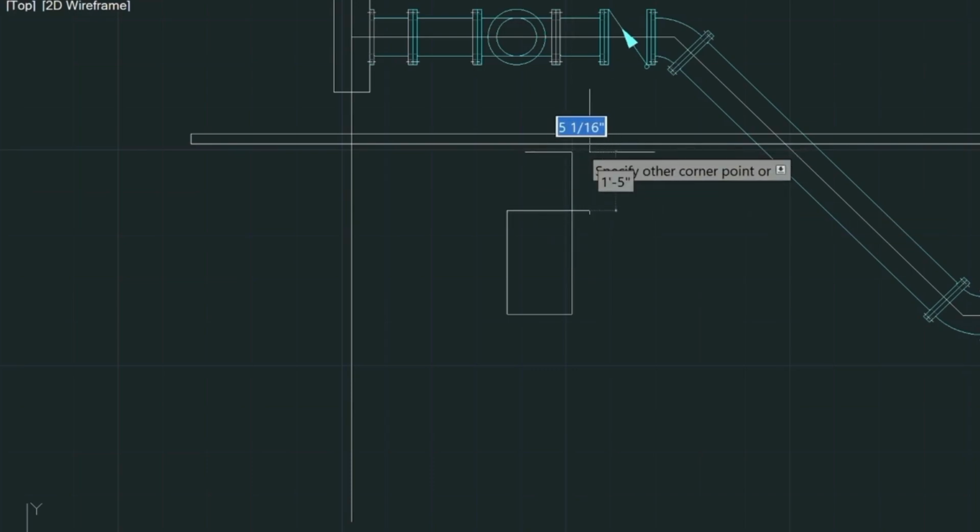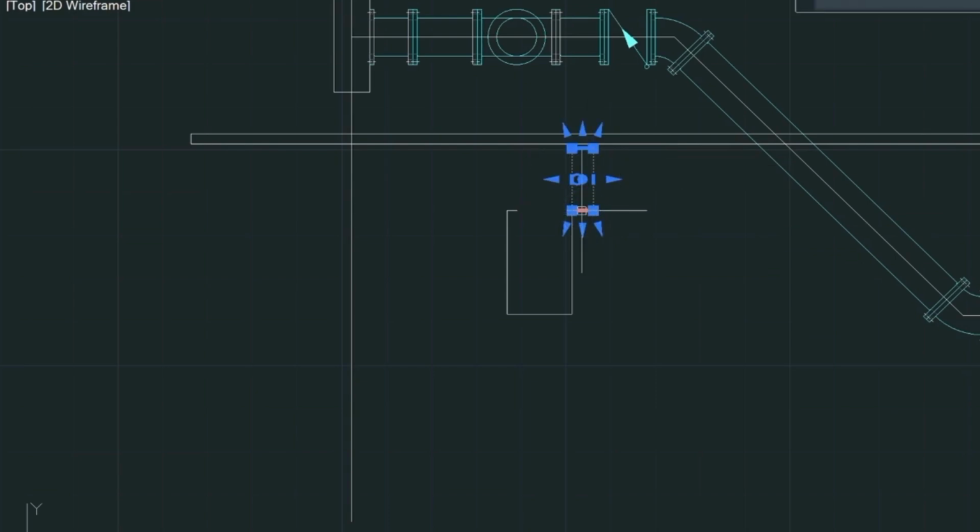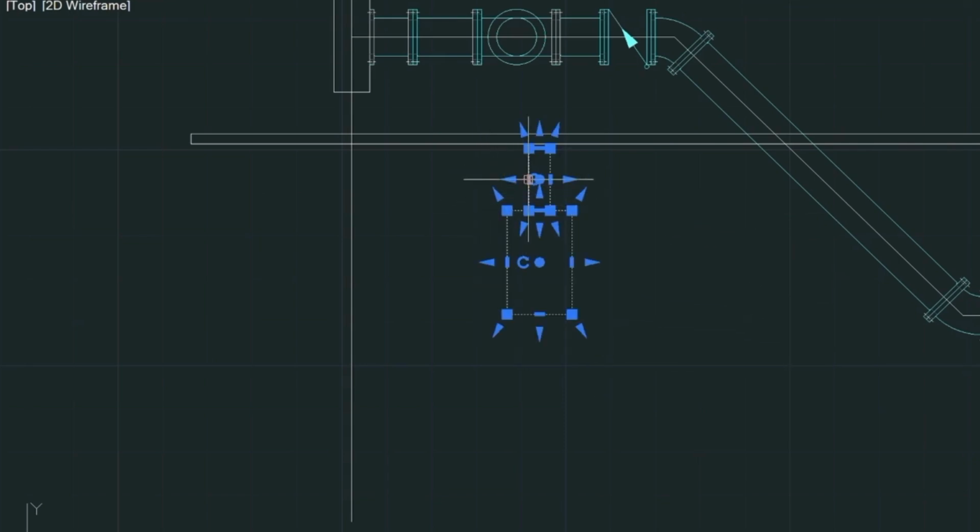For a pipe support, REC, we'll just snap it over here. Draw this at 6 inches and 1'6". Again, we'll just move this over, snapping it to the middle. And then we're going to move this whole piece up. I selected it this way from the lower right to upper left, and that will pick up anything in the crossing. I'll pick it again from the grip, and let's support it right here by clicking on the midpoint.